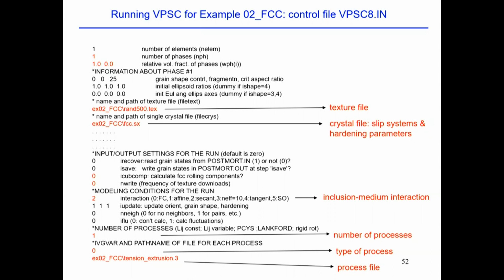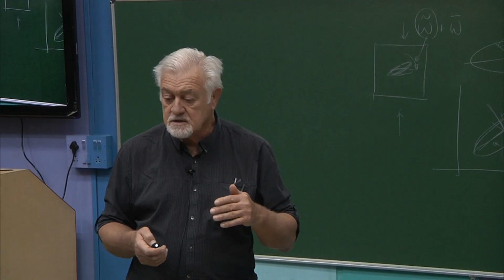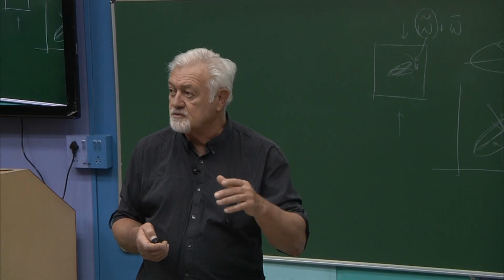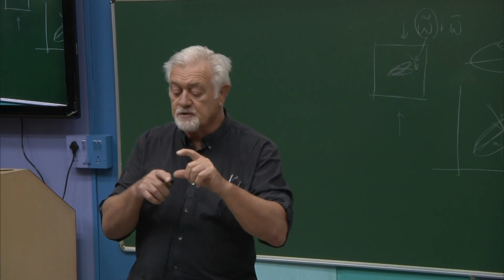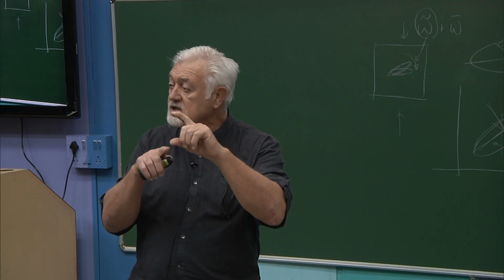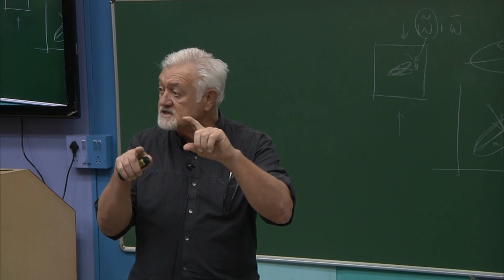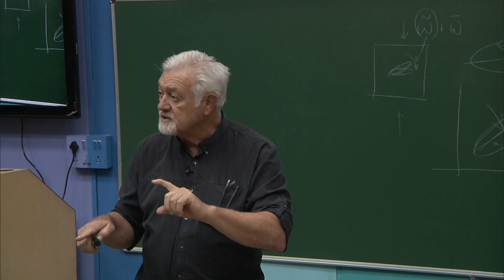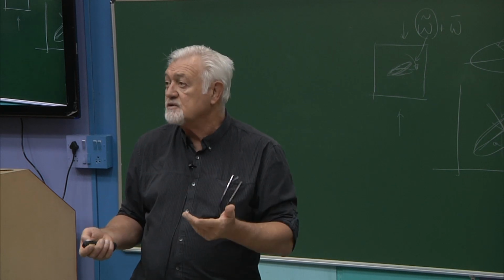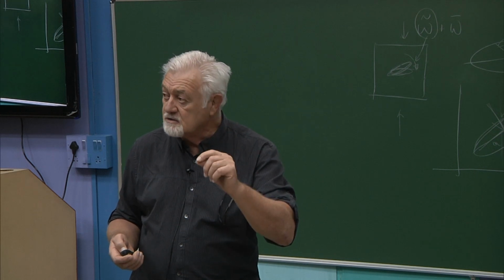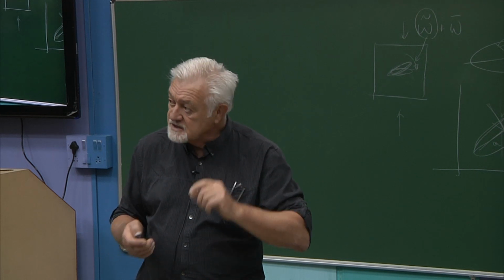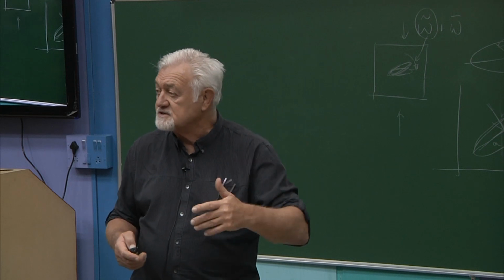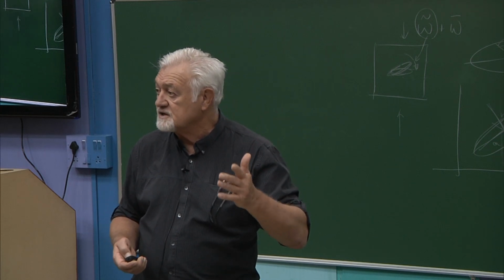For example, you can do tension up to 50%, and at that point say, okay, calculate the polycrystal yield surface, and then do 50% more of tension, calculate again the polycrystal yield surface. So that would be 4 processes: 50% calculate polycrystal yield surface, 50% calculate. So you do 100% tension with 2 calculations of polycrystal yield surface.